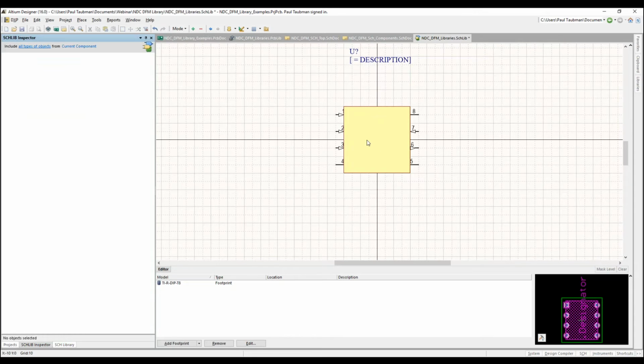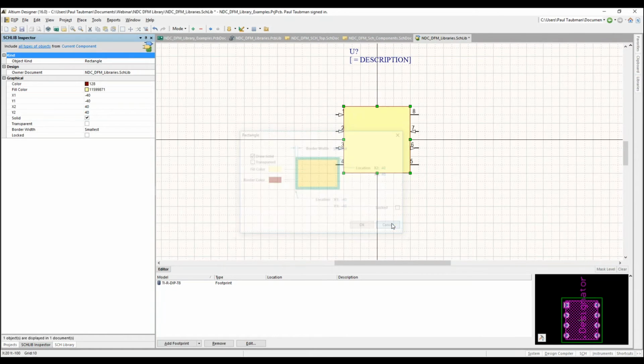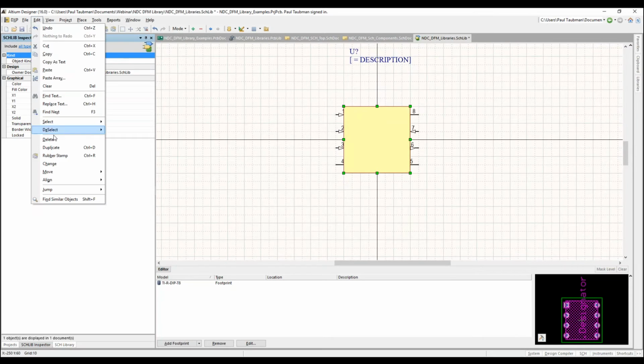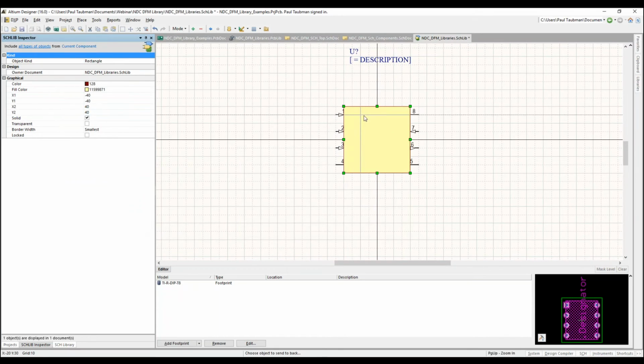And we have 2 ways of changing this over here. We can either push it to the back, or we can double-click into it, and we can make it transparent. I'm a bigger fan of pushing it to the back because when you do things on printouts, that order of operation can have an impact on the way the printer responds. So what I'm going to do is go to Edit, Move, and Send to Back, and I'm going to click on our triangle, and boom, now it's done.